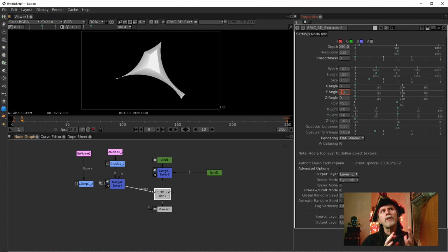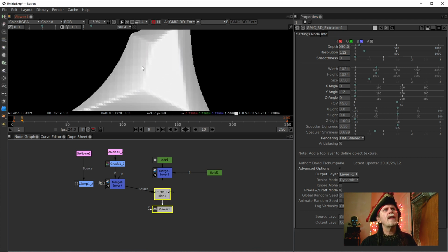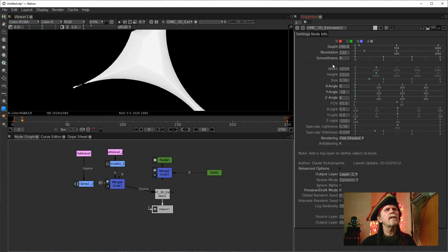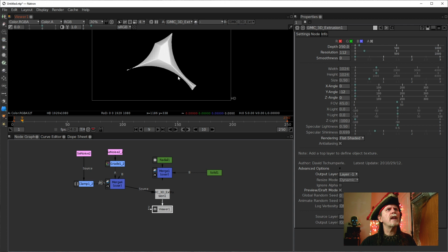So you can see this is not going to be limited to just doing simple poly shapes, but if you do something more along these lines, where you define a shape, this is going to take a lot longer. So what we would want to do is probably drop something like this down in resolution, to around 100. Even at 100, we're getting a lot of broken up. If we look at this really close, we can see that there's funky things happening in here. It's looking a little weird, and broken up, and it's not shading quite right.